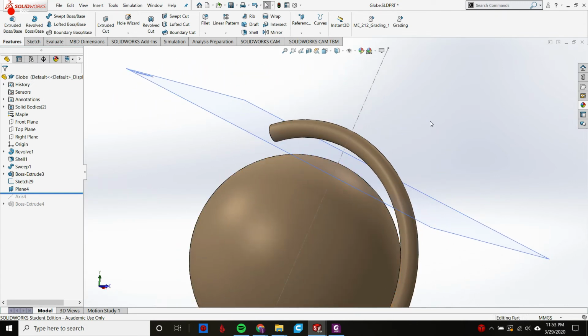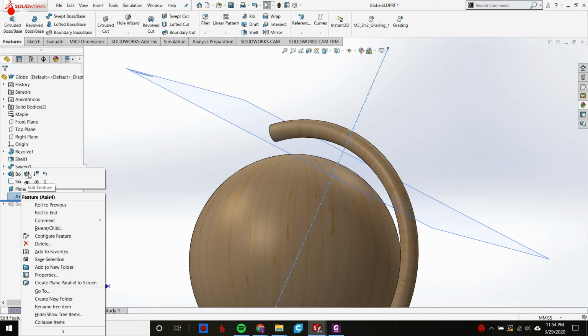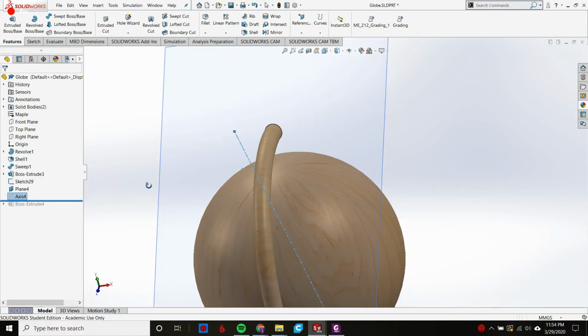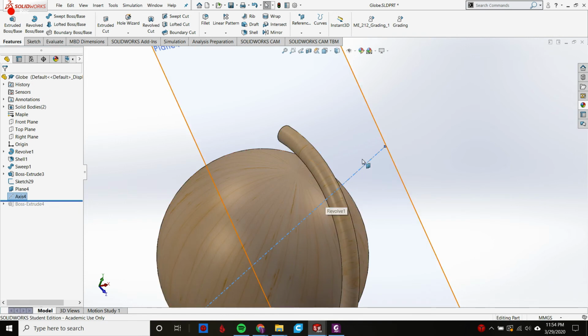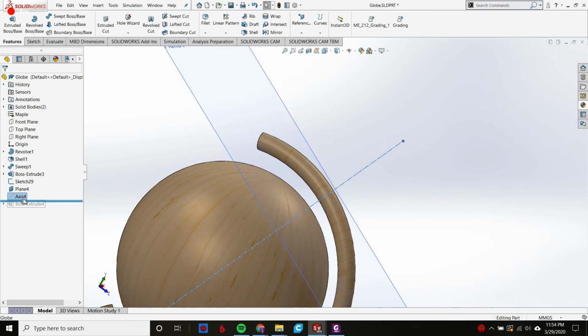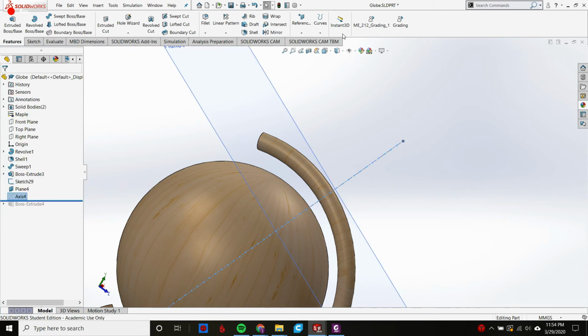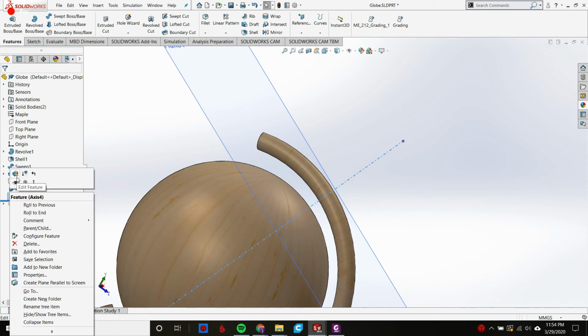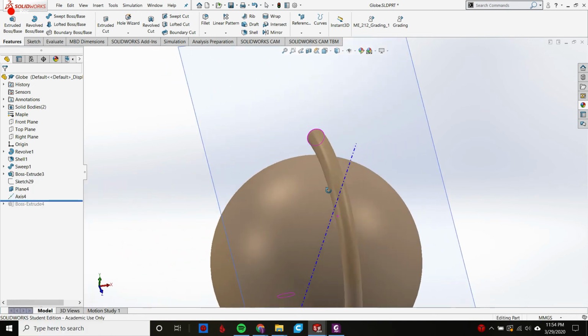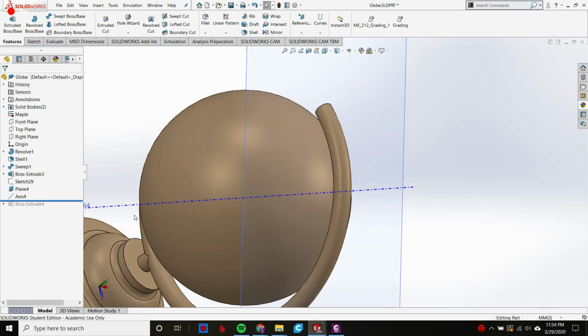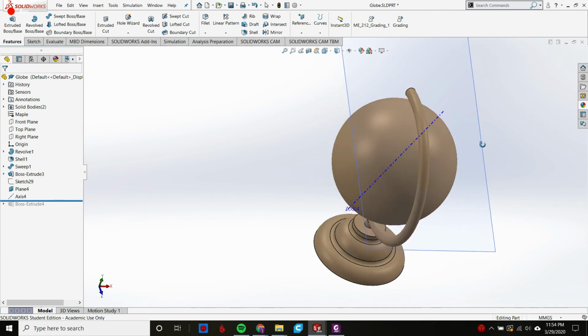And then I turned this guy into an axis. What that allows us to do is relate to it, right? Because if you're sketching on this plane, you can't set relationships between what you draw to another sketch's line. So I turned it into an axis, and what I did for that, super easy, is I just chose the axis. You come up here and choose axis, and then I just clicked on this line. If we hide this and show this, we see that we now have an axis in its place, and it's bright blue, which tells us it's reference geometry. You can see it's labeled axis number 4, because I tried this a few times beforehand.